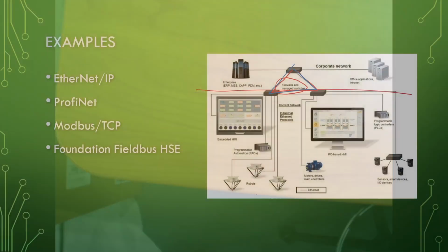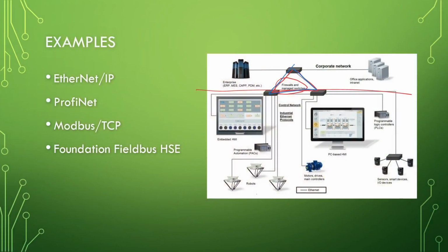Well, anyway, on Allen Bradley PLCs, there is a little circular port. In this case, it's embedded like right here. There's a little cover that goes over it. There's a place for a cable to come out, but that is our communication port for this PLC. It used to be if you wanted to program this, you had to have the special cable that would reach all the way down in there and plug into serial. They did actually have little adapters, so you could plug in there and put that on the network. But that was how they did it.